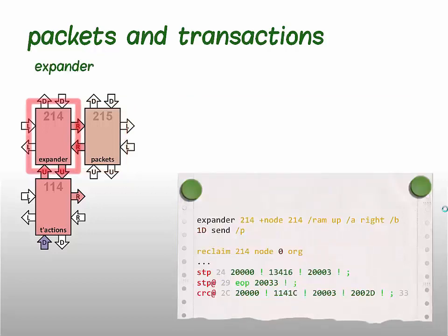Node 214 is responsible for extracting individual bytes from compressed packets. There are also definitions of commands, which are sequences of actions that are used in multiple packets. When we encounter a command in a packet description, we call its address with pushx instructions. In case of the setup packet, we execute word stop, which contains a command for the serializer and CRC calculator in node 115 to execute from its write port. Then we send a call to word clear, which clears the CRC calculator. And finally, we send a command to the encoder in node 216 to generate end of packet.